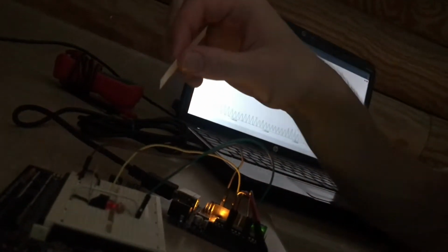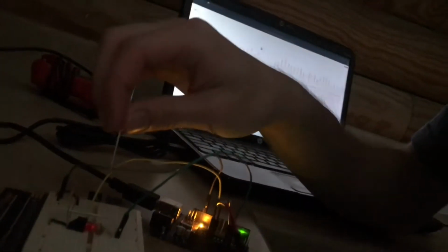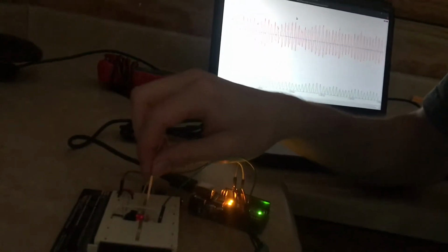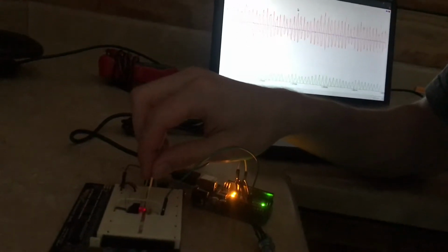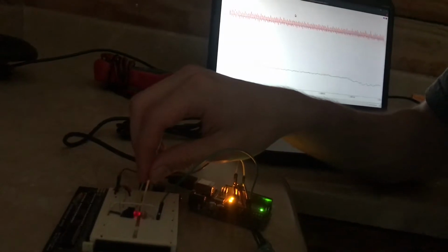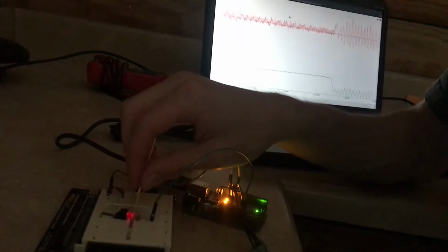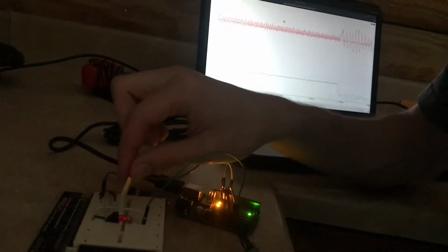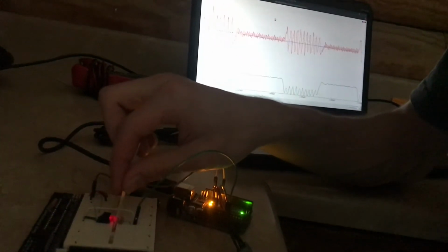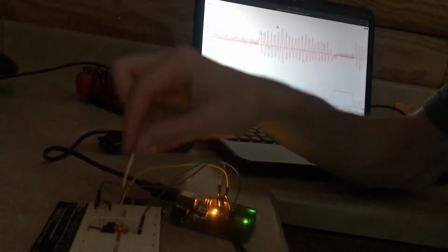I wanted to see how well this system handles change. So as a curveball, I turned the lights off, and I have the set point fairly low, so only a small amount of light should be allowed to hit the sensor. But whenever I put this piece of paper in, you can see that LED gradually got brighter depending on how much of it I block. And of course that's because only a fraction of the light is able to pass through the white paper, and so the LED, in order to maintain the same brightness on the sensor, has to get a little bit brighter.